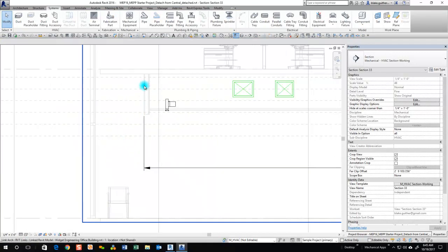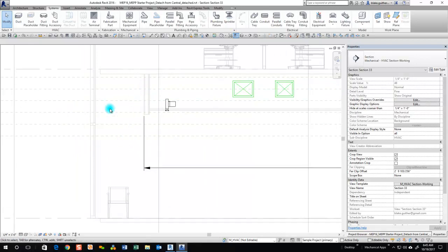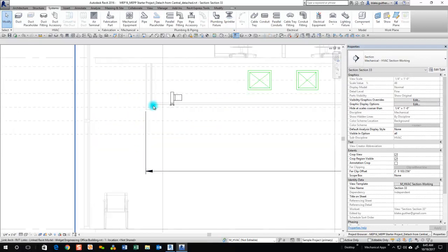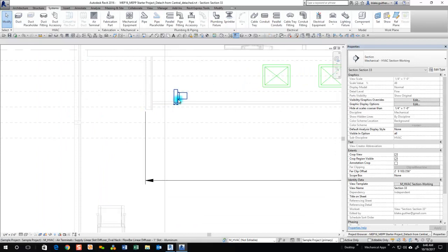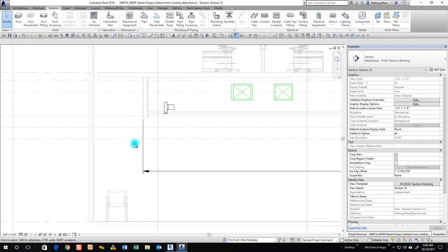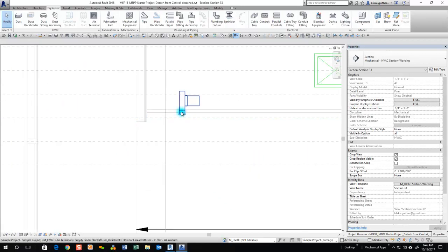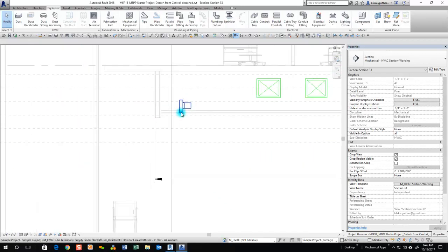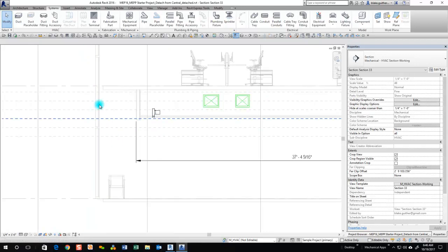We could do a surface mounted linear bar grill up here and maybe angle the airflow down at 15 degrees. This little ledge isn't very appealing to using linear slot diffusers. However, for the sake of this being an auto-sizing linear slot diffuser demo, we're just going to plan on this type of design. So we're going to be throwing air at the window horizontally and to wash this face of glass.